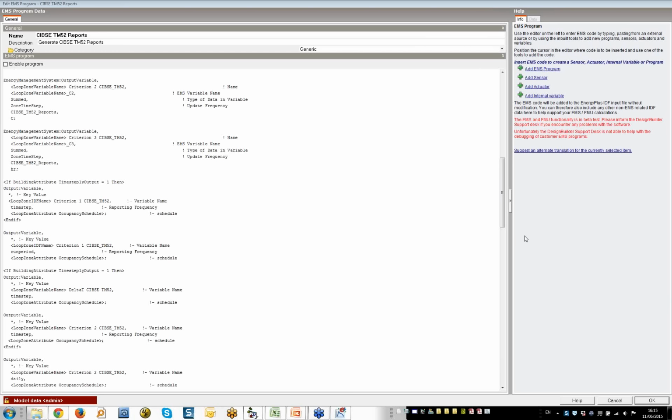There's a question here also about climate-based daylight modelling and whether we can provide the results that are required for version 4. We've been working on this recently, actually, and version 4.5 beta does include the spatial daylight autonomy outputs. And so we've got that already working. And we're currently working now on providing the annual sunlight exposure outputs, which we expect to make available later this year. So by the time version 5 is released next year, we'll have that all working and tested nicely.